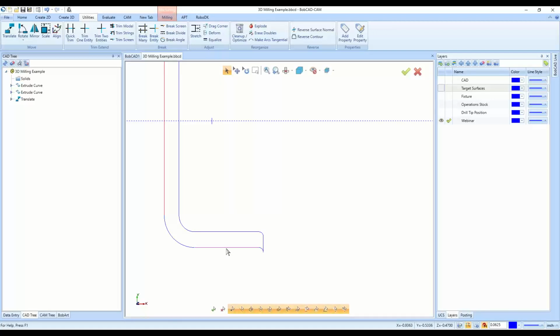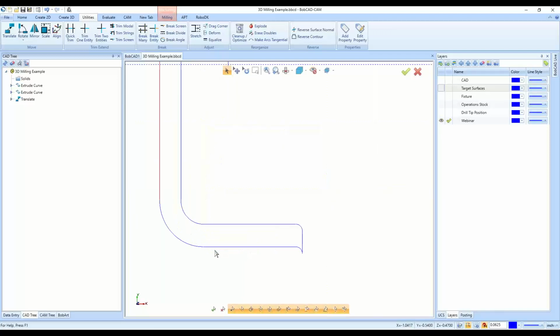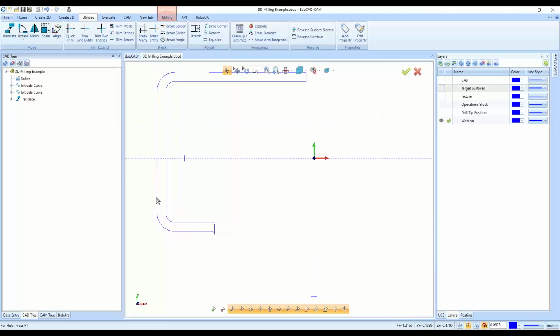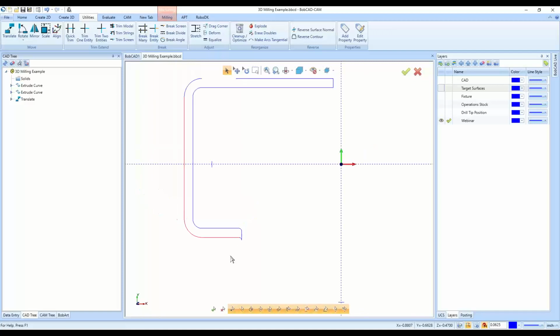You want it to go around clockwise. You hold Shift and click to the direction where it's going to end. And if you want it to go counterclockwise, just this line, this arc, and this line, you hold Shift and click on the line somewhere in this area from the halfway mark.